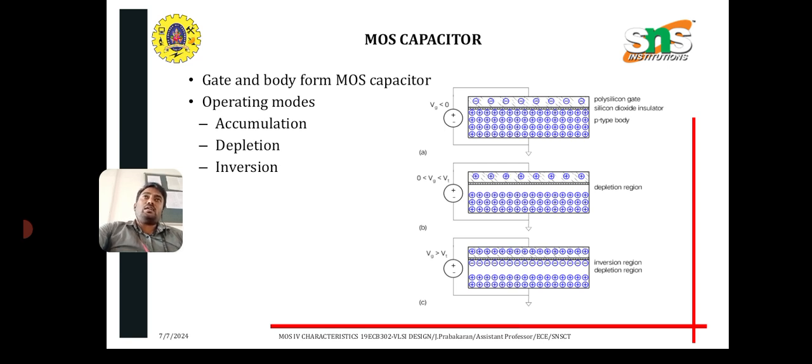We already know the operating regions. What are operating regions? What is meant by operating point? I will give an operating region introduction. There are three types of region: cutoff region, linear region, and saturation region. When the gate source voltage is below the threshold voltage, the transistor is non-conductive and no current flows between drain and source terminal, which is called the cutoff region.